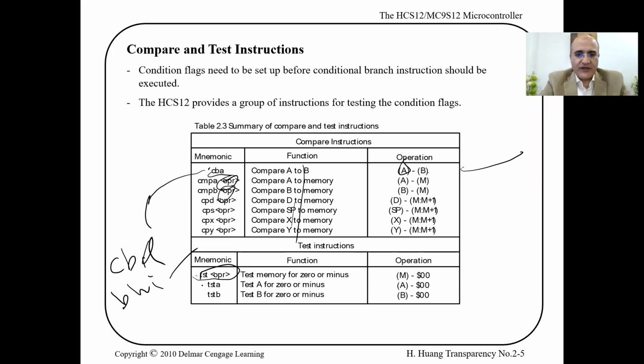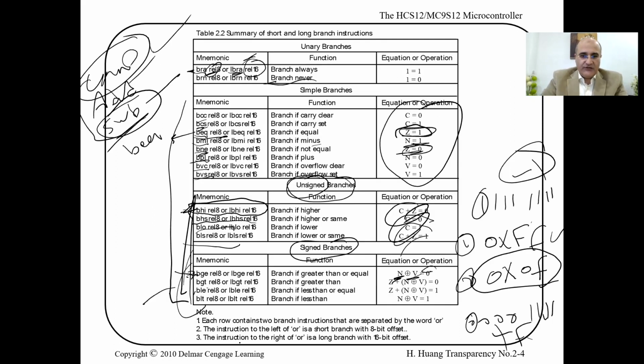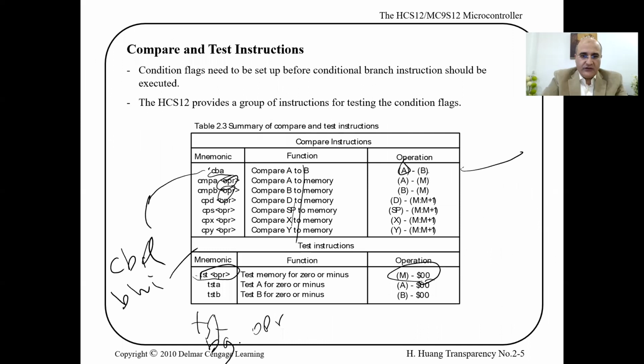The test instruction: TST operand. You subtract a 0 from a number. If after it you use, for example, branch if greater, BGT, so if the operand is greater than 0, meaning positive, you'll do a branch. It will be true. If it was less than 0, this will not result in a branch. You continue, meaning false.